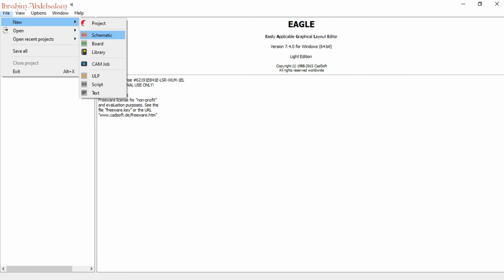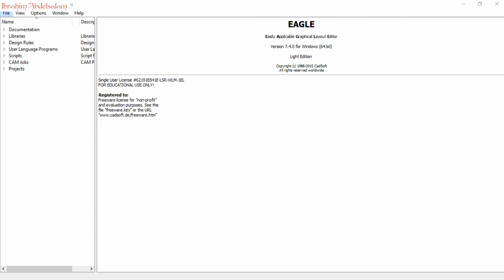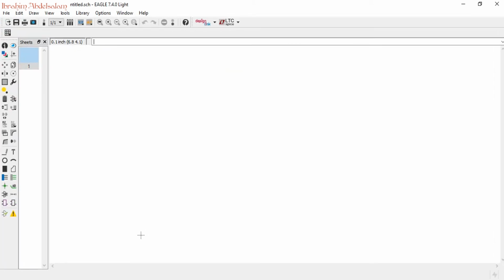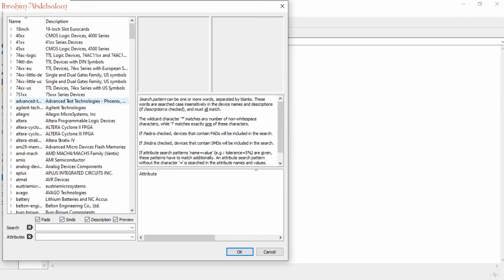training. Now, new schematic. We will build a 5 voltage power supply, so we'll have an AC input come from a step down transformer from 220 voltage AC to 6 voltage AC. Then we'll add a diode rectifier followed by a capacitor, voltage regulator, small capacitor, and output. Okay, I will estimate that the transformer is outside the PCB, so I will need a connector.